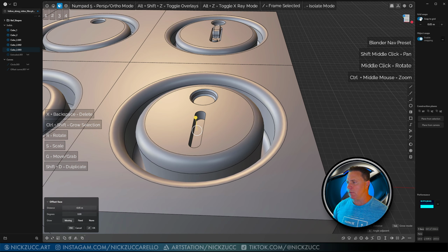So I'm going to go straight down this way and mirror it across there. And if I hit OK for that, we can do that. And now it's basically split this into 2 different objects. I'm going to do the same thing again, where I select this, I hit Alt X, tap F for freestyle. I can go back into this midpoint, and I can go right here like that and hit OK. And then basically I've segmented out this corner.